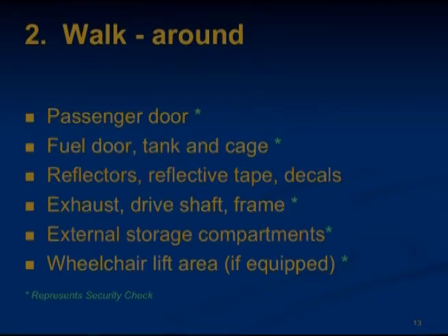Check that the reflectors, reflective tape, and emergency exit decals are intact and not damaged. Underneath the bus, sight check only. The exhaust system, check it for sagging exhaust pipes, tailpipes, and mufflers. Look for visible exhaust and soot. Listen for excessive exhaust noise, vibration, and rattles. The drive shaft should not be damaged. Couplings need to be secure and free of foreign objects. U-hangers need to be secure and not damaged. Make sure that the frame is not damaged and nothing is unusual or attached to or under the bus.